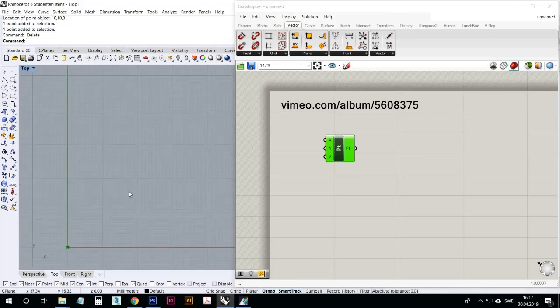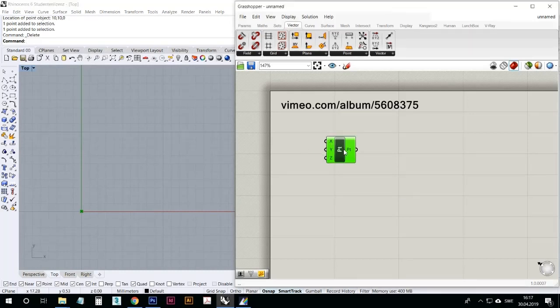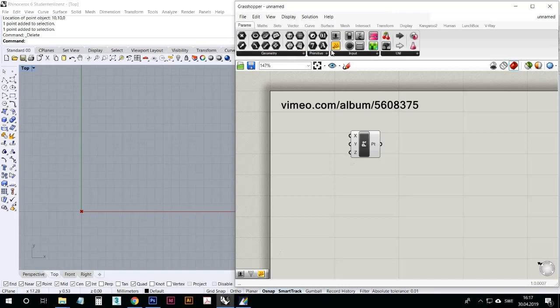That's the question, because the question about position has already been answered, right? That's why you now should hover all inputs. So X coordinate, there it says 0. On Y coordinate, it says 0 as well, and on Z coordinate, it also says 0. So this means you can put your own inputs here. The easiest thing to do is to use sliders. You saw before that you can also take out this panel, double click it and type something, and never type enter afterwards, by the way, because if you do this, it's going to break the command, the code line.